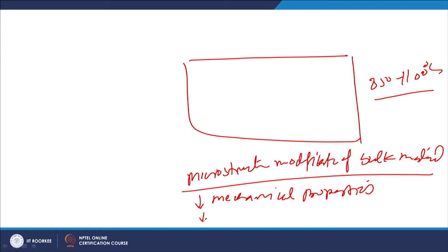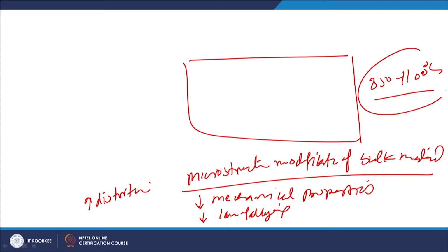The second problem is that exposure to too high a temperature for longer time can lead to the loss of alloying elements from the bulk material. At the same time, it also increases the tendency for distortion, an undesirable change in the size and shape of the component. The main origin for all these undesirable features associated with cyaniding, carburizing and nitriding is the high temperature for longer time.